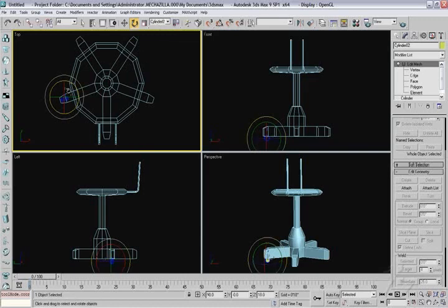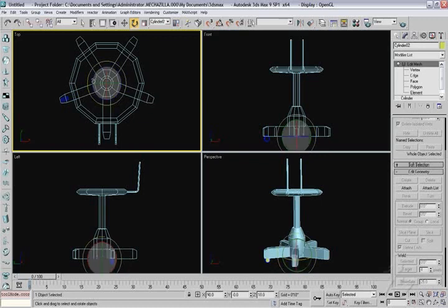Now at this point you can see based on the transform gizmo it's still going to rotate on the local coordinate, even though we have that under our list. What you need to do is actually go by that pivot point. So next to that is the Use Pivot Point button, hold down that, and choose the very bottom one, which is Use Selected Pivot Point. As you can see, the transform gizmo will now go based upon where our original cylinder was based.